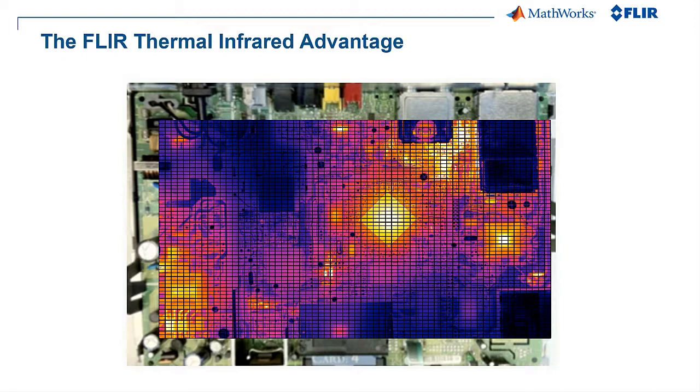Which, as you mentioned, in some instances, especially with printed circuit boards, when the targets are very small, if you apply a thermocouple to that target, you could actually change the thermal characteristics or properties. The thermocouple, in a sense, becomes a heat sink, which is what it's designed to do. Yeah. And as you mentioned, it's like having several thousand spot radiometers or thermocouples when you have this calibrated thermal image. In fact, this particular image is made up of 640 by 512 pixels, which is over 300,000 individual measurements.